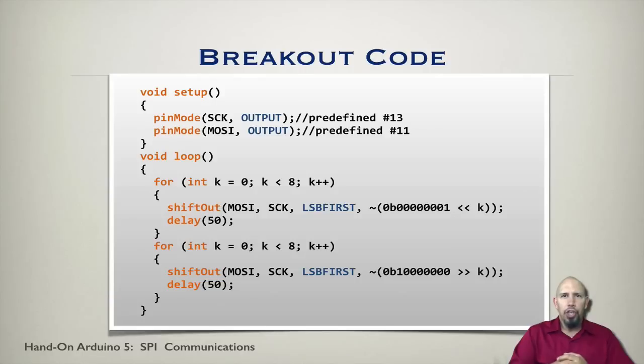some people prefer to use a TTL chip that has what's called a latch associated with it that actually holds the data constant and prevents that flicker that I was talking about. Some people prefer that. If you have the problem of flickering, then you may want to consider something like that. But it comes at the expense of requiring an additional bit.